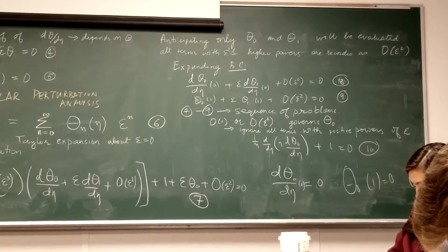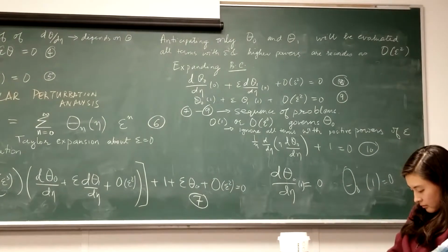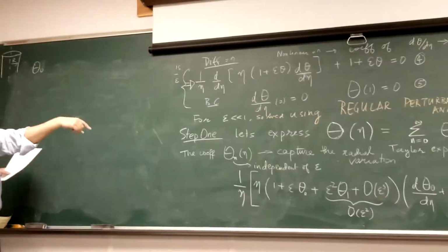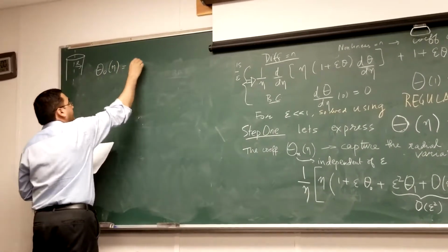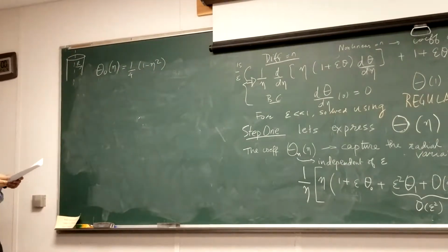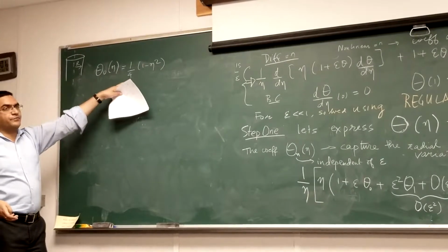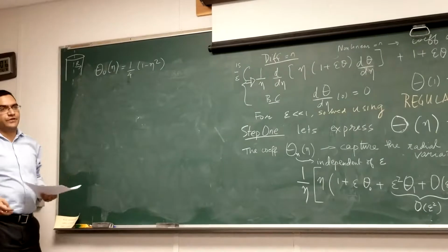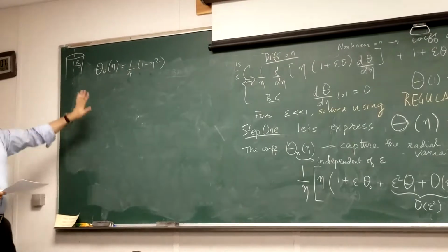and if you remember it, what you'll find is that solving this with those two boundary conditions gives you theta naught of eta as 1 over 4 times (1 minus eta squared), and this was the solution when you had a Biot number much greater than 1. The prefactor is slightly different from the prefactor you had in the previous problem, and that is because our scaling is slightly different, but it still has that parabolic dependence, right? So I now know theta naught.